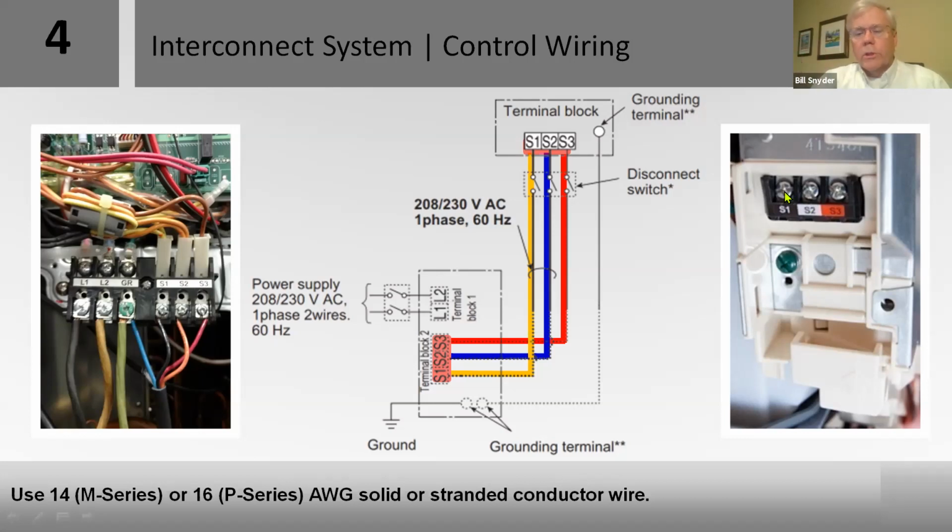Stranded wire squishes down, so you get a better connection on it. It just works so much better. Here's the outdoor unit. You've got your L1, L2 and ground, and your S1, S2, S3 on the outdoor unit. Go to S1, S2, S3 on the indoor unit.